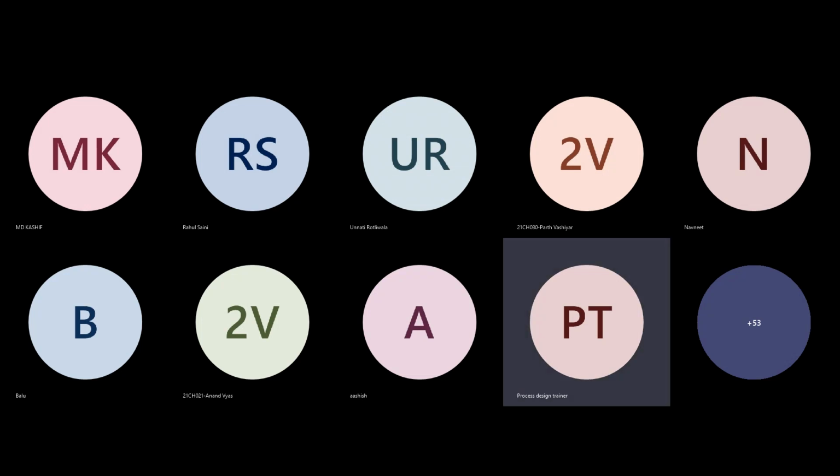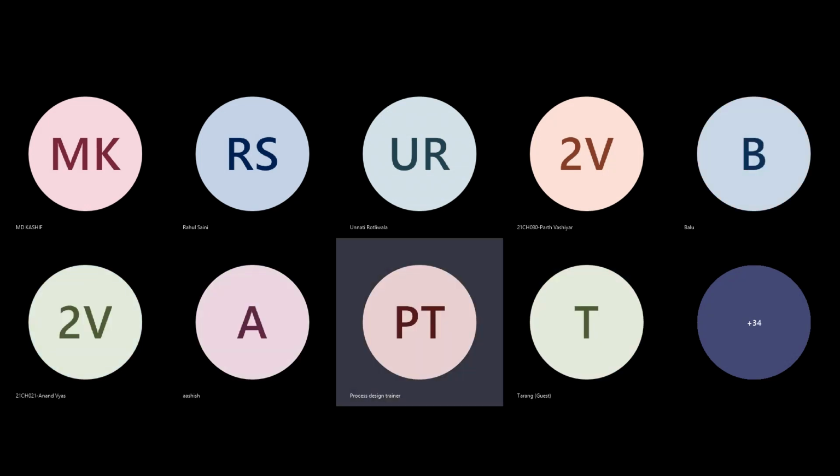Suppose there is no liquid level because it is underground, there are no frictional losses, so frictional losses are zero. And suppose your water is at 0 degrees centigrade, so there is no vapor pressure. In that case, NPSH available is 10.33 meters. That is basically the pressure of the suction tank; your underground tank is at atmospheric pressure. If you use all that NPSH, and your pump is at the ground floor, then you can suck the water from 10 meters depth.